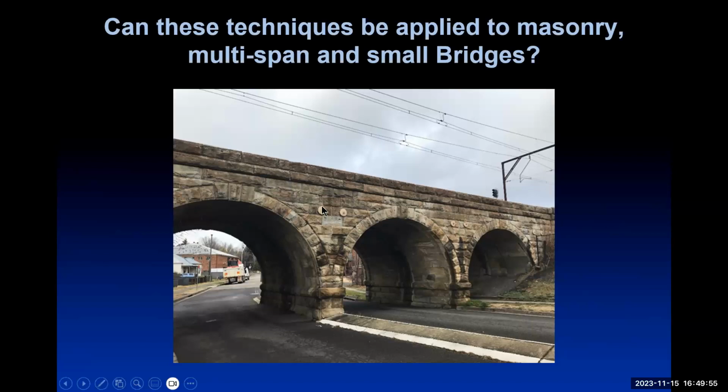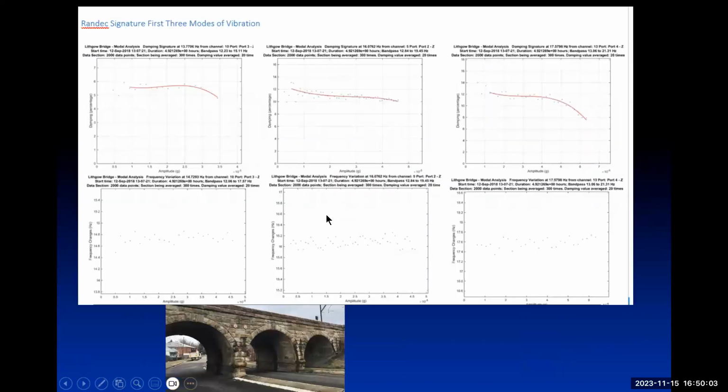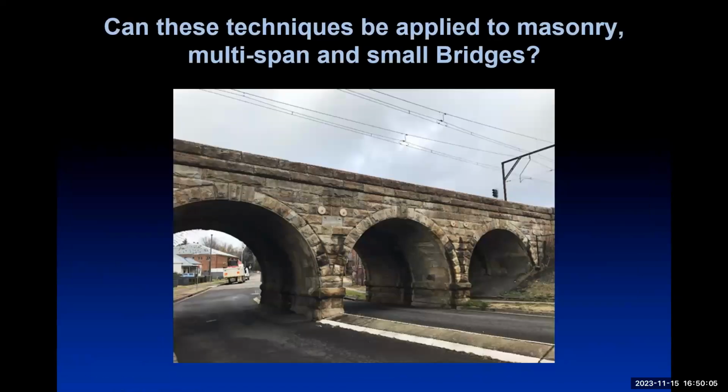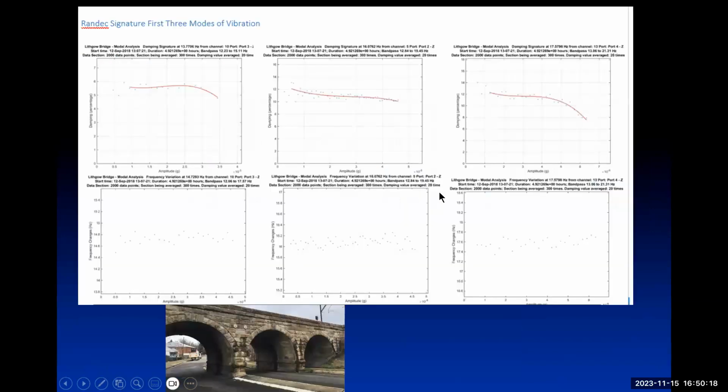And in practice, it was in a very poor condition. They assumed there had been stiffness elements added to it. And what we found was modes of vibration doing this sort of thing, incorporating motion in one span, two spans, three spans there.